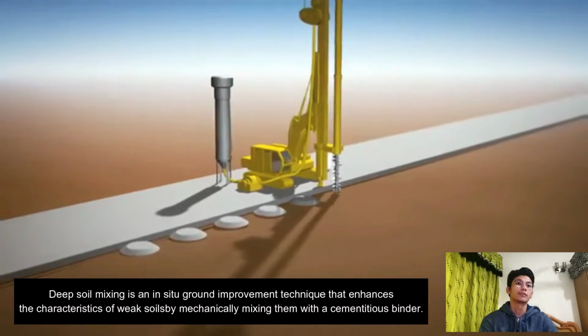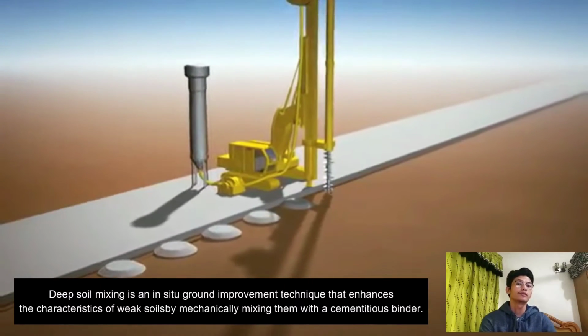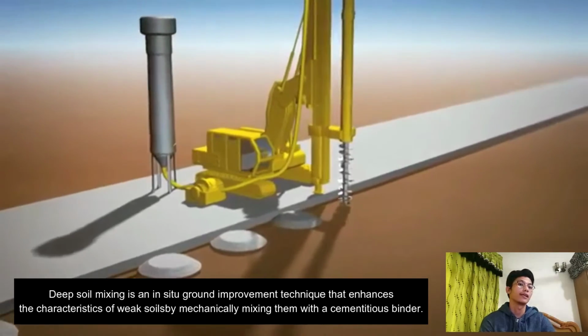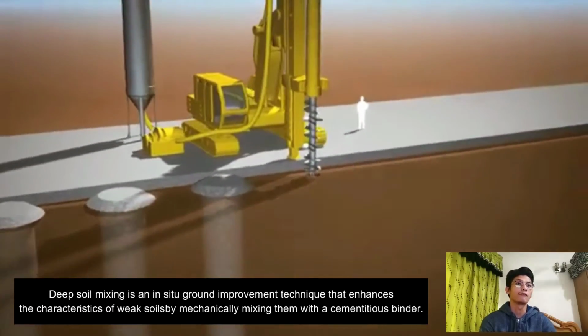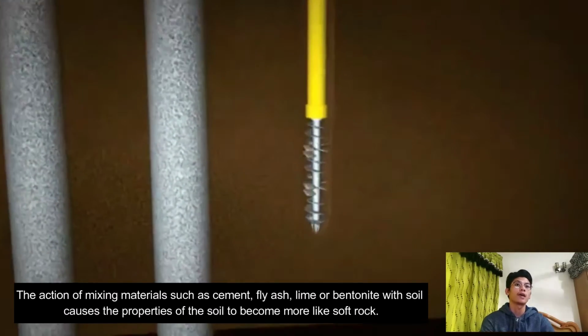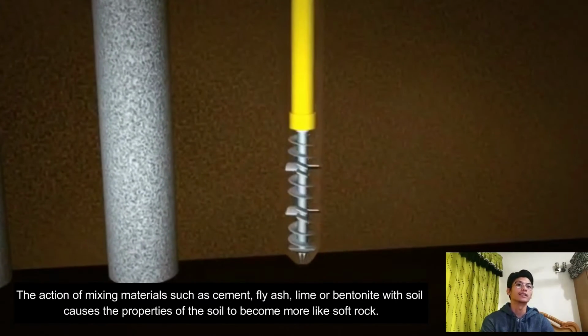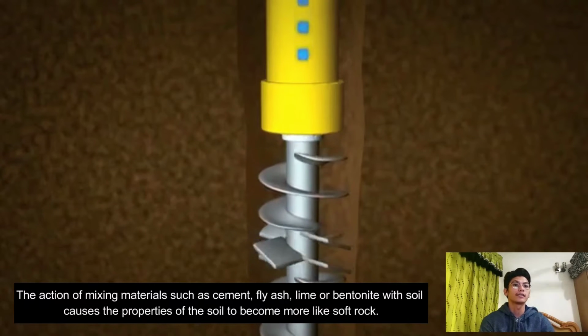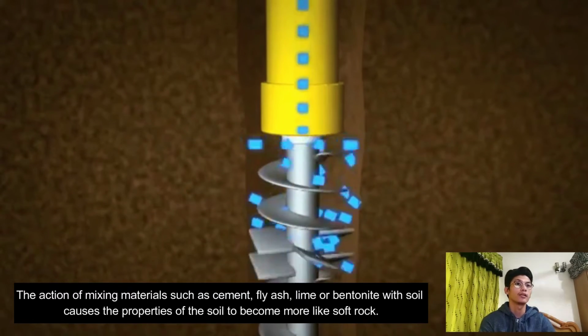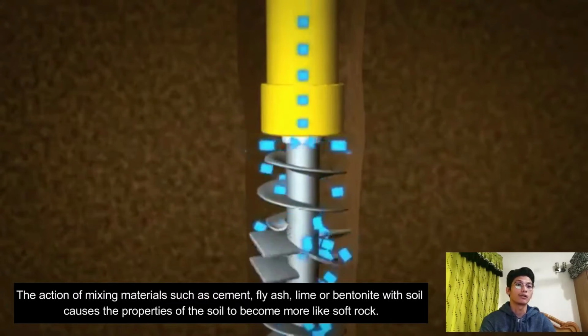What is deep soil mixing used for? Deep soil mixing is an in situ ground improvement technique that enhances the characteristics of weak soil by mechanically mixing them with a cementitious binder. The action of mixing materials such as cement, fly ash, lime or bentonite with soil causes the properties of the soil to become more like soft rock.